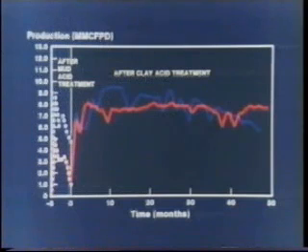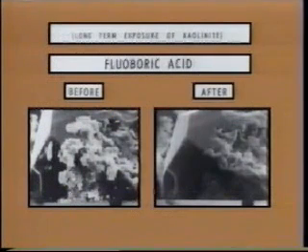Fluoboric acid is another inorganic acid. It can remove clay damage and sustain production increases in cases where mud acid has failed. For example, as shown with a scanning electron microscope, the effect of fluoboric acid on sandstone is to dissolve the kaolinite material while leaving the quartz material relatively unaffected. In addition, fluoboric acid stabilizes clay material and prevents fines destabilization and subsequent pore clogging. Fluoboric acid procedures and effects are documented in the technical literature.